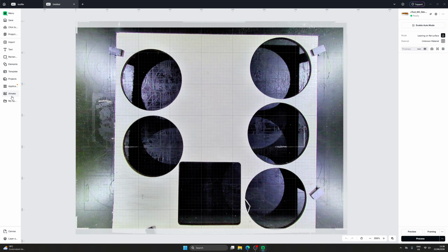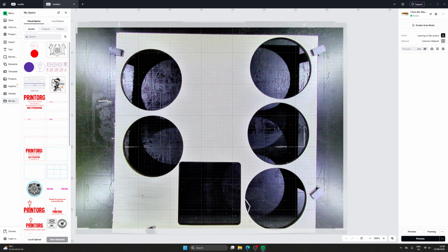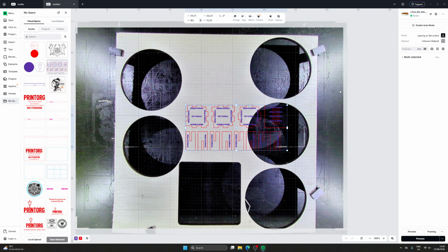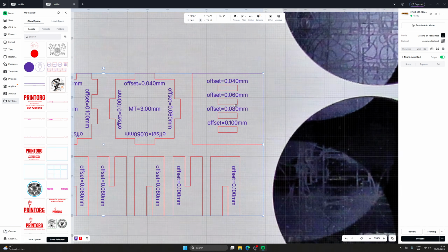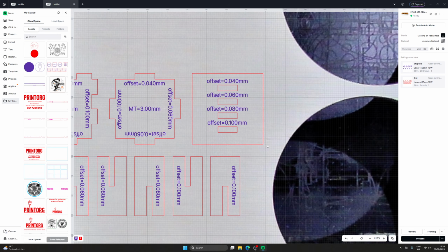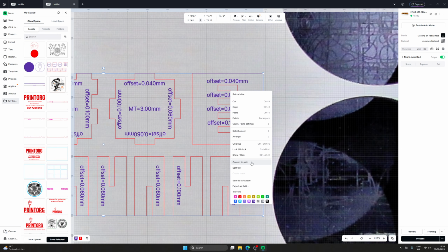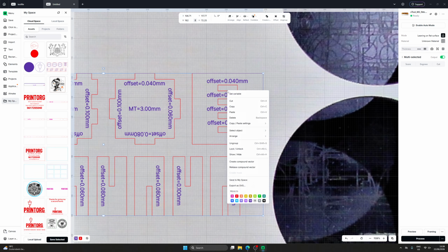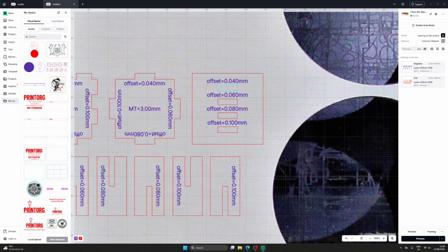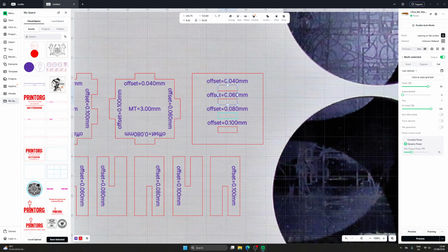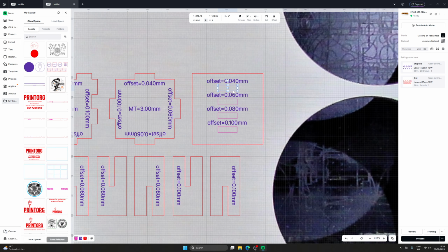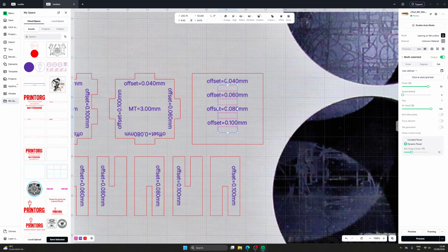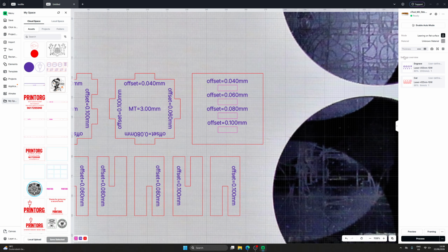We'll open a new tab for you guys, just to make sense of it. As you can see on this one, you want the squares cut out before the main square is cut out. So you convert these to the path, ungroup it, and then I can select these squares and put them in layer 1. Then I just click layer 1, it'll select all of them, and put them on a cut. And then it should be cut before it starts the outline.